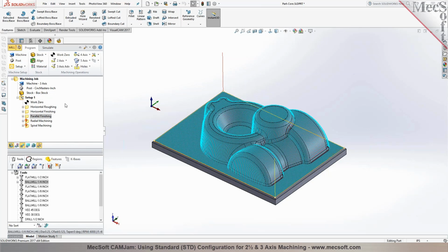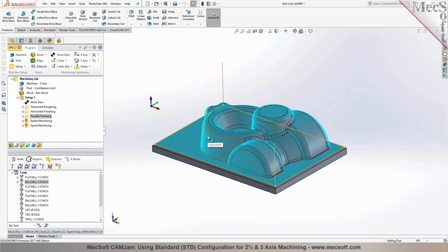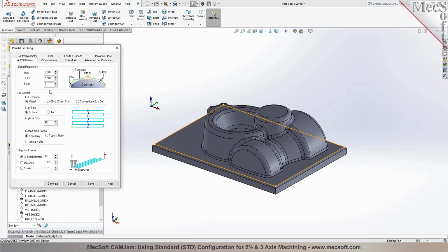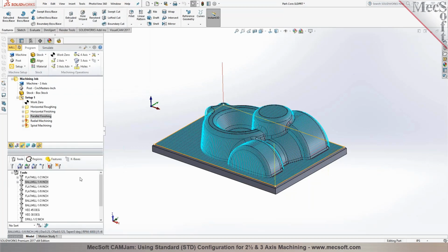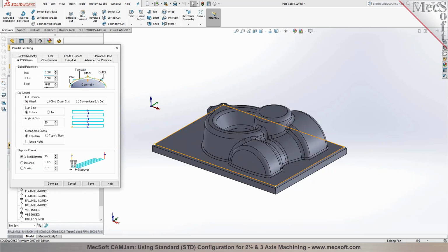Now, if you wanted to do it in the CAM, we have tools where we can shrink the part. If you want to shrink one of them, you can do it. Here you can specify what is called a negative stock offset. I can say I want to cut 10 thousandths into the part, so shrink the part overall by 10 thousandths. That can be done in the toolpath itself. But ideally, you would want to do it in the design process when you create the two halves. Sure.